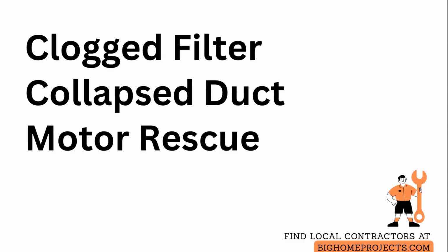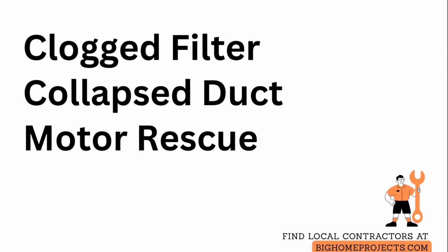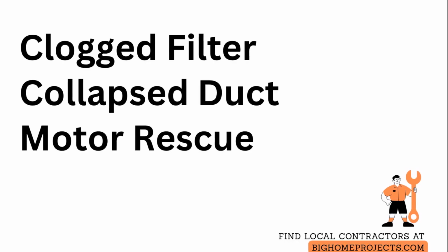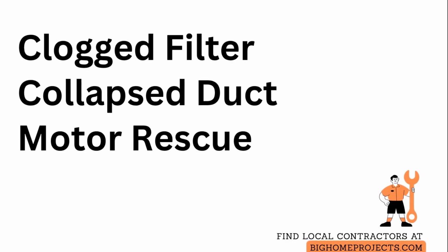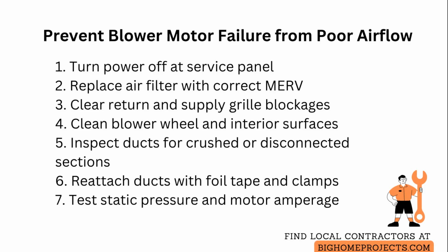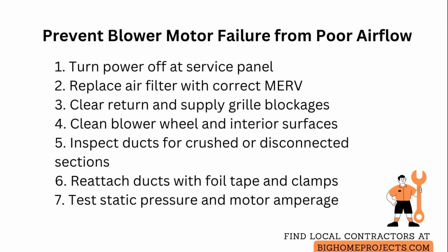A clogged filter or collapsed duct can, and often does, cause blower motor problems by restricting airflow and forcing the motor to work harder than designed. When airflow is restricted, the blower motor draws more current and runs hotter, which shortens component life and can trigger thermal cutoff devices. Start by turning power off at the service panel and then remove and inspect the air filter.